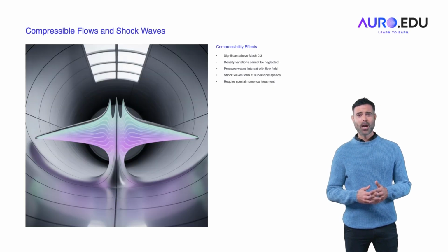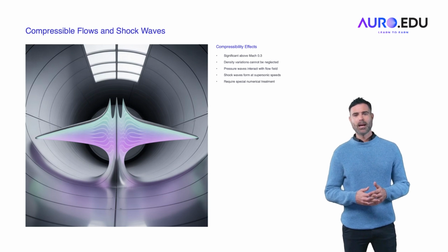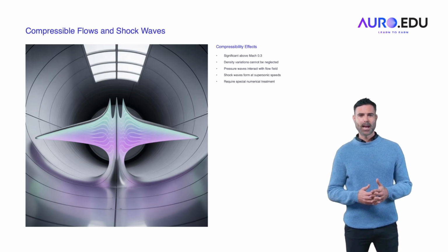Compressible flows and shock waves. CFD plays a key role in understanding compressible flows and shock waves at high speeds. Compressibility effects become significant above Mach 0.3, where density variations can no longer be neglected and pressure waves interact with the flow. Shock waves form when an object travels faster than the speed of sound, creating discontinuities in flow properties such as pressure, temperature, and density.